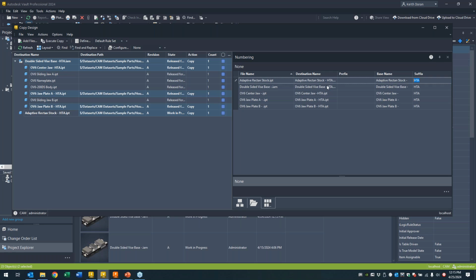Renaming files within the vault, copying these components like this, it's never going to break a link. In fact, we typically tell people, once it's vaulted, if it's vaulted clean, it stays clean forever. So in this case, renaming them, moving them around inside of my vault structure, none of that really matters. It's going to reference and update itself accordingly. So in this case, I've specified how I want to rename these files.